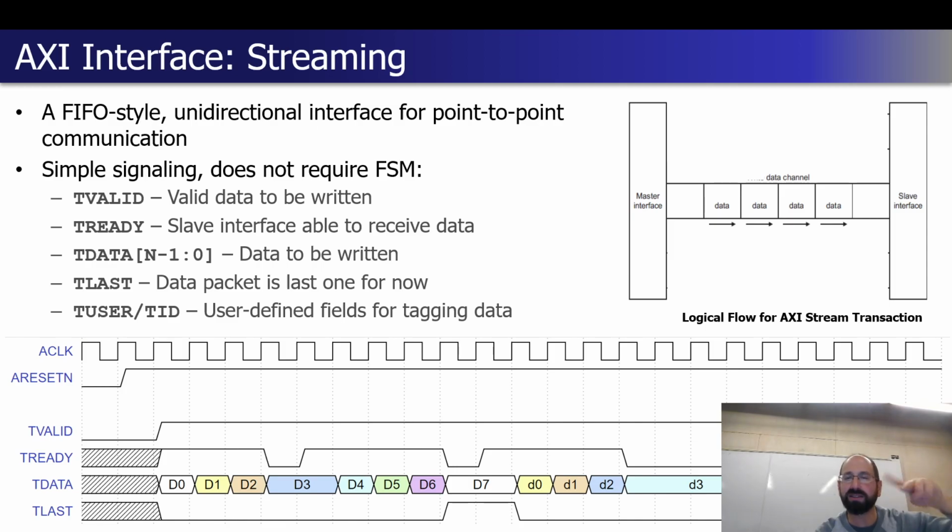That little mux or switch we showed a couple weeks ago, where one buffer is the front, one buffer is the back, and we just switch them back and forth each time. That's just an address remapping, so there's no actual physical switching happening there. But somebody has to tell that particular IP core it's time to switch. And I don't tell you how to do that. That's one of the things you'll have to solve, kind of a last debugging step for MP1.